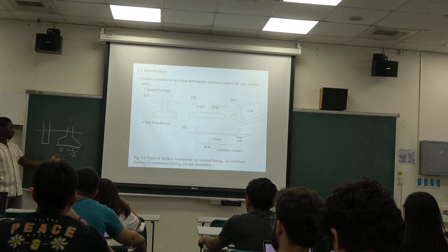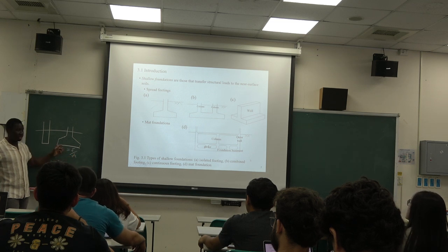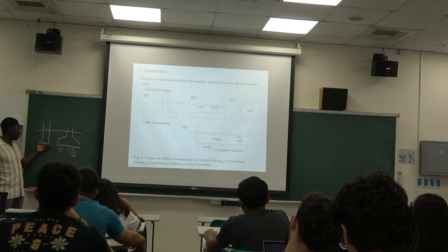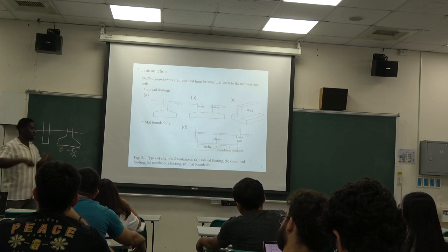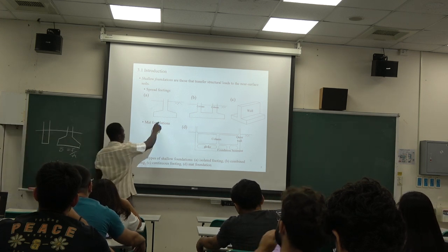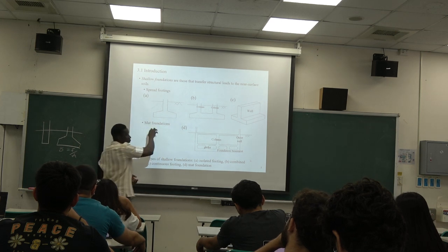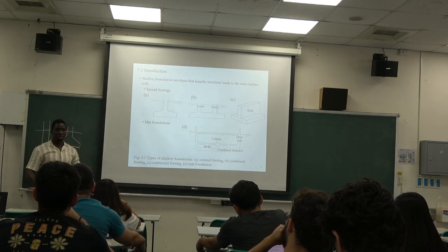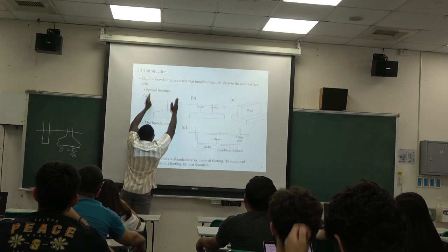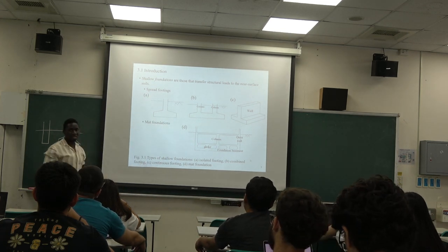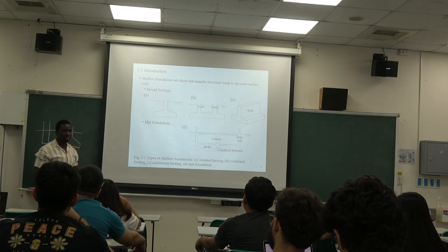So the larger the area, the more it can distribute the stress. But if it is like this, it can easily cause failure, because the stress will be significantly higher. That's the whole idea about spread footings. You just have a footing which will help you distribute the loading. Or you can say, how about we just make it this big? That's okay too, but it's not economical.